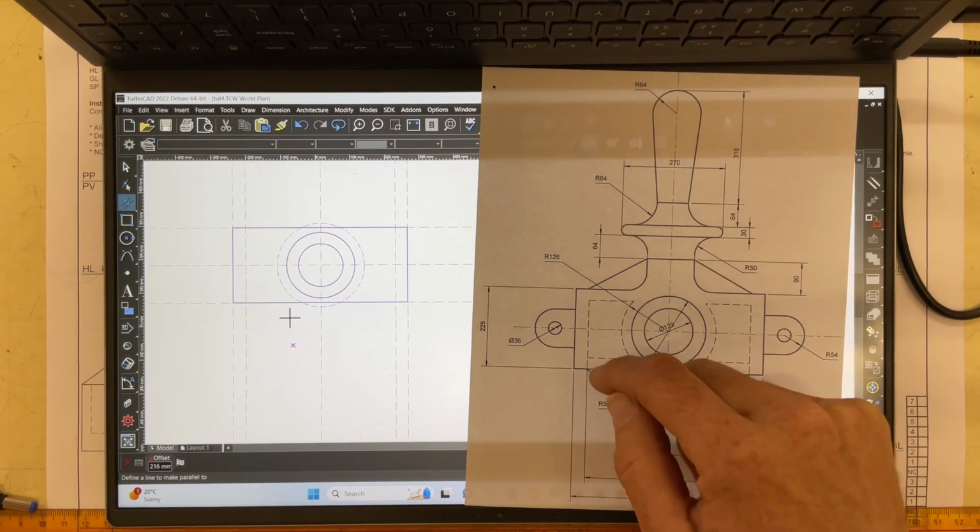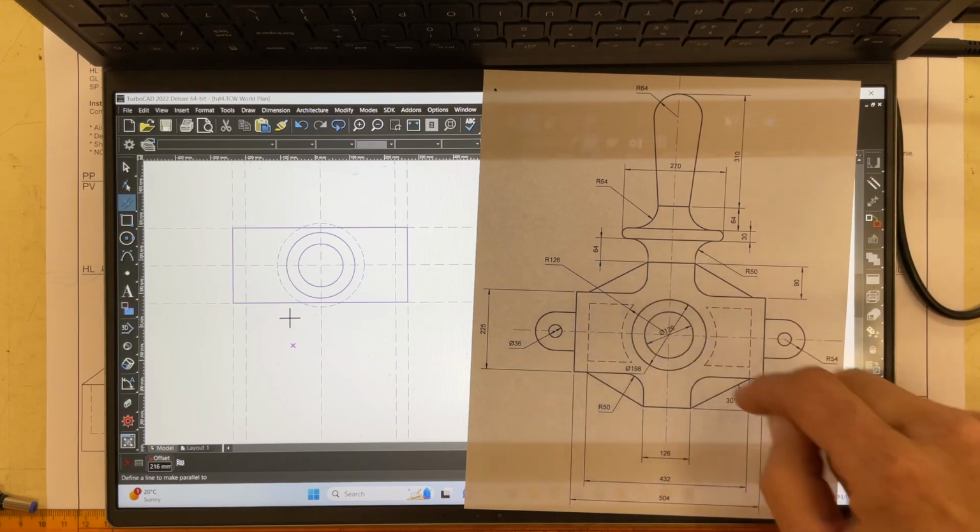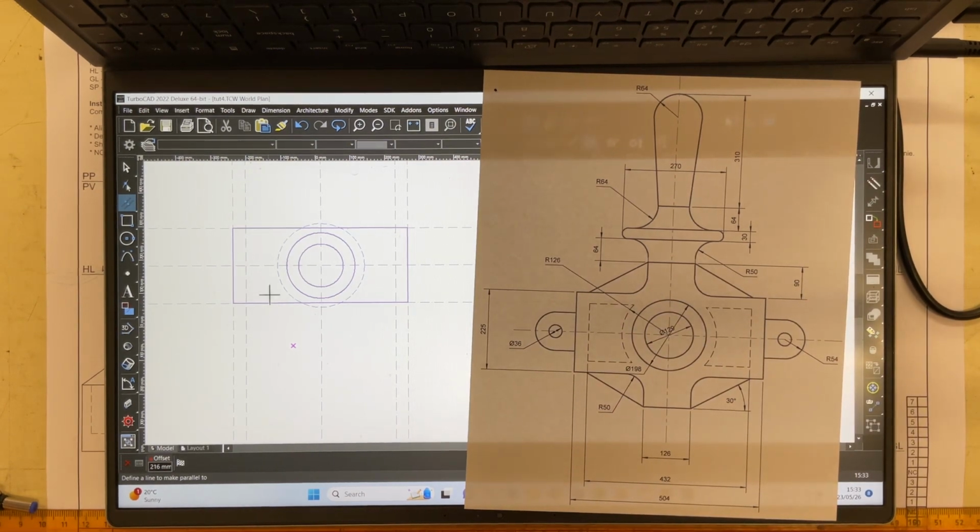Now you'll see that it's an equi-spaced sort of gap all the way around this thing. How do I find that equi-spaced thing? Probably the quickest and easiest way, go in there, select the angular construction line, go to this corner over here, and then you can see the slant over there, type in 45, tab, 45, enter, escape.